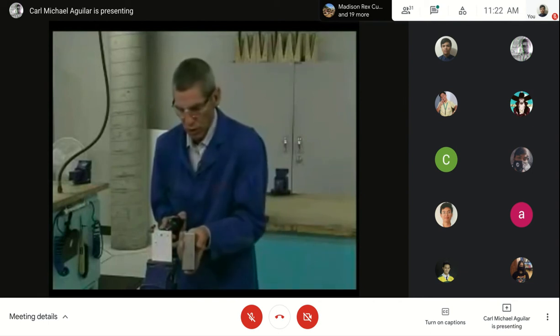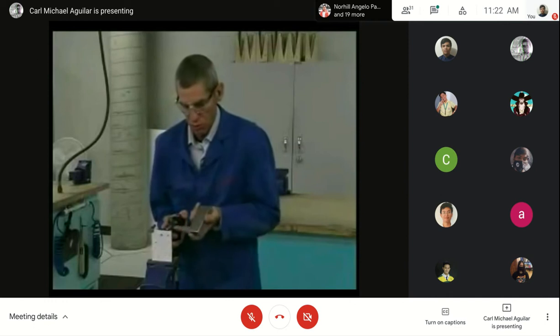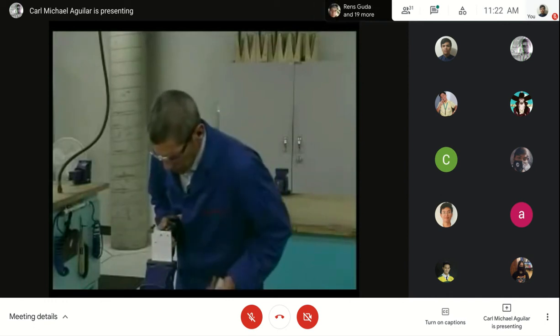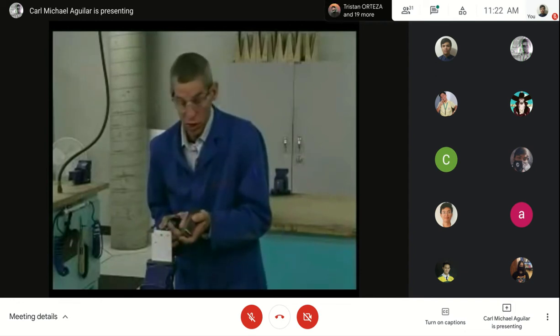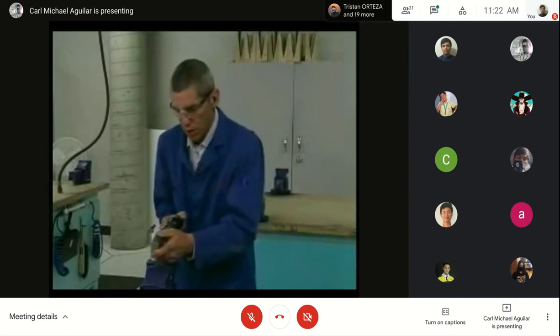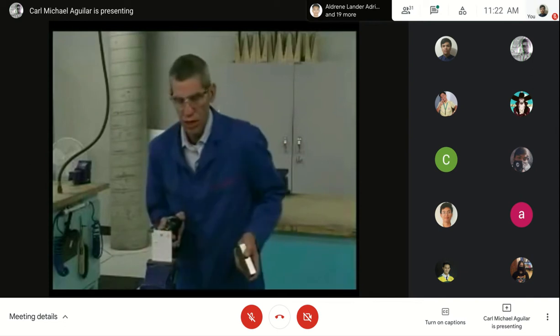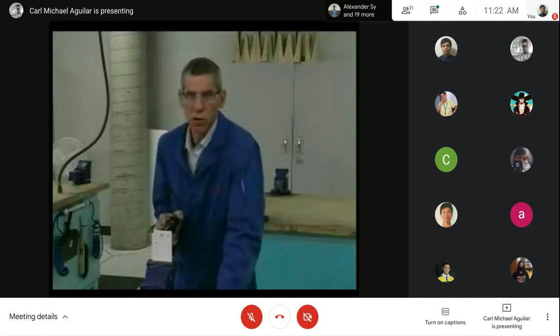Stop. Remove the bucking bar from this side here. The riveter could keep the rivet gun onto the manufactured head, and you take a look at the other side and you see, is it enough or does it need more? It's always a good idea to stop a little bit earlier than it is to over rivet right off the bat. In this case here, I can see I need a little bit more, so give it another short burst, and that's the riveting process.